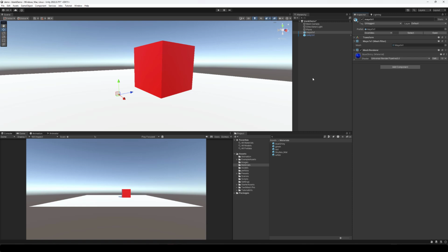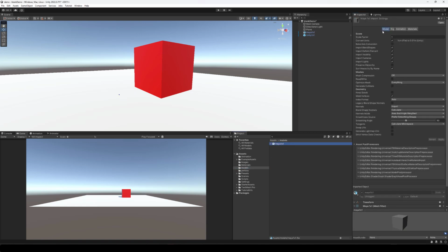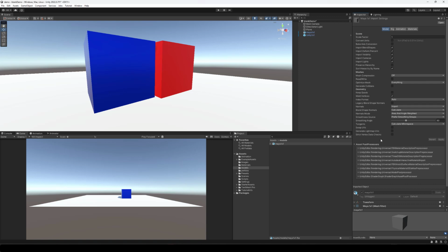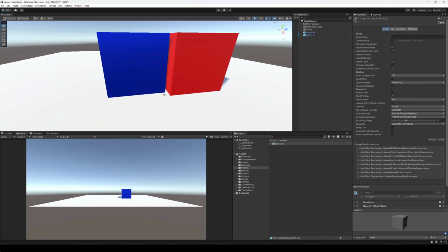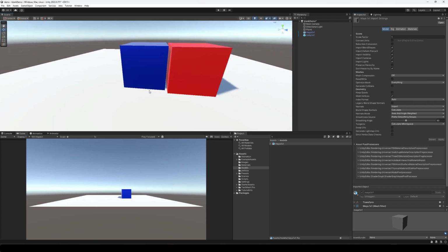In Unity, select the model in the projects folder. In the inspector, you'll see some tab-like boxes at the top. These allow you to adjust the imported object. With model selected, you'll see a scale factor of 1. You could type in 100 there, but instead, I uncheck the Convert Units box and hit Apply. It's pretty simple, and I've never seen anything strange using this method. Scale is very, very important.